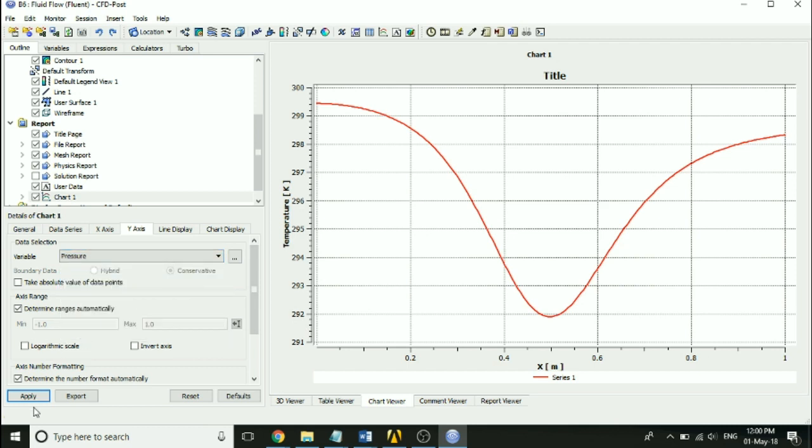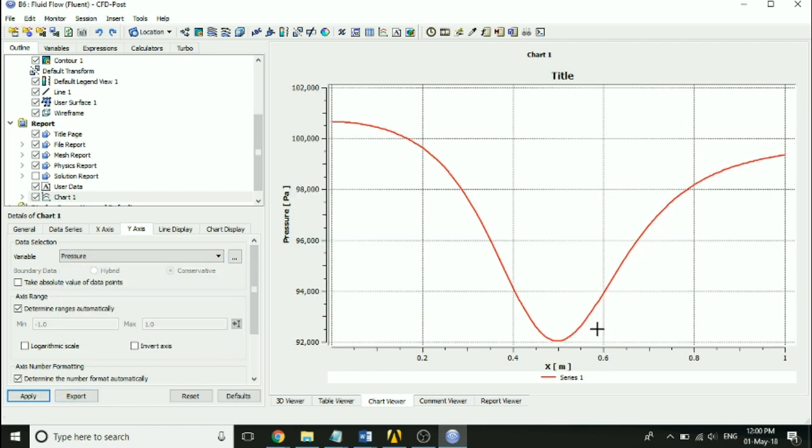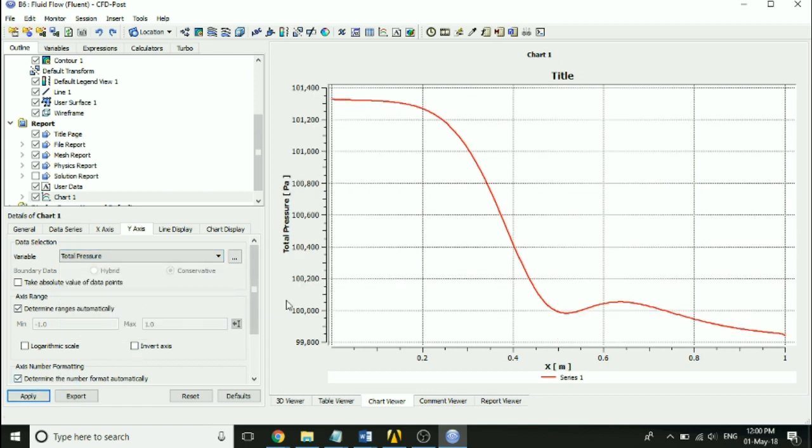Let's see pressure. Let's see total pressure. Now it should be steady after the throat, since the pressure increases almost steadily. So you can see here, because static pressure increases whereas velocity decreases, it will behave steadily. The total pressure will behave almost steady since they cancel out.